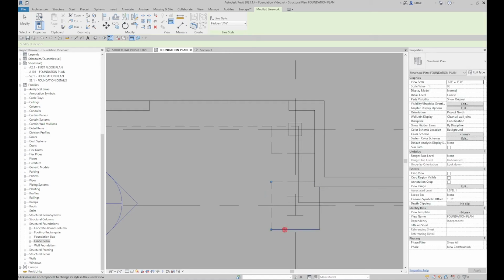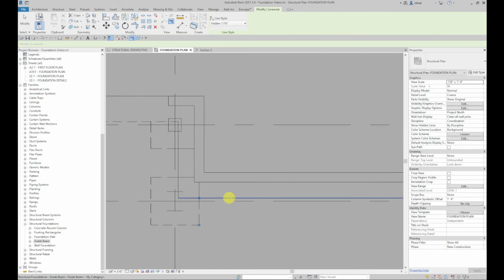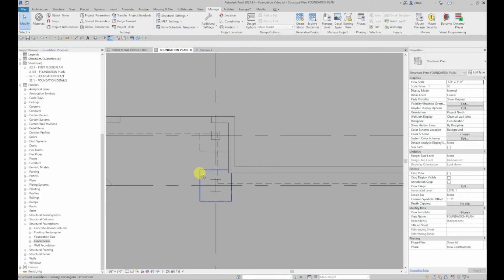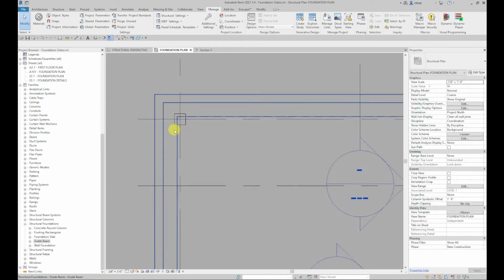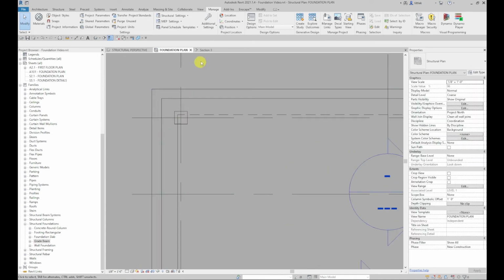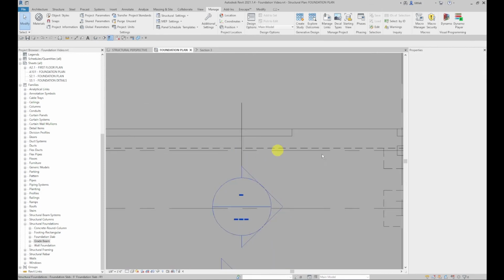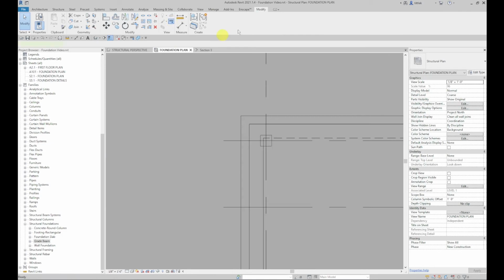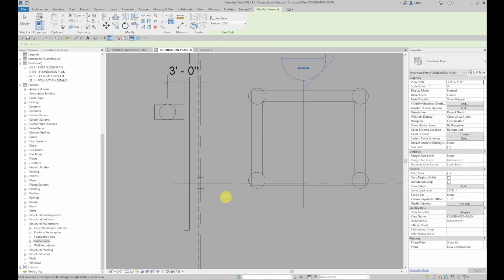So I'm tabbing into some of these to get the right line. So this one is going to be this line here and this line here. And that's how I force the lines of a 3D object to be different, using that line work tool. So again, that's modify, line work, hidden 1/16 for this face. Oops, see, it is a little finicky. You got to make sure that you're only clicking the lines that you want.